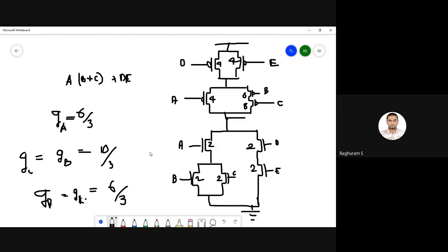So this is the logical effort for a complex gate, AOI or OAI, and this can be different for the inputs because it's not symmetric like a NAND gate or NOR gate. Some branches have more transistors, some branches have less. So in the end, since we want the 2 and 1 for the whole networks, we have to size them accordingly, and then for each input we see. So if you want to ask what is the logical effort of this gate, if I want one number, then you have to mention the worst case, that is 10 by 3.